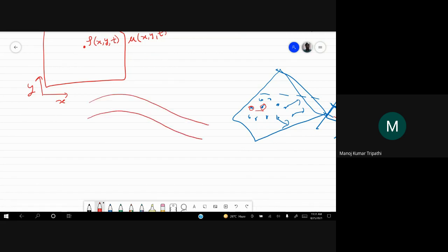Let's say this is a pipe. The area of cross section here is A1, and the velocity perpendicular to this is U1, the average velocity. And here the area is A2 and the velocity is U2. Then there is a relationship between all these quantities A1, U1, A2, U2. Can you write the relationship, the continuity equation, assuming that the density is the same throughout the pipe?